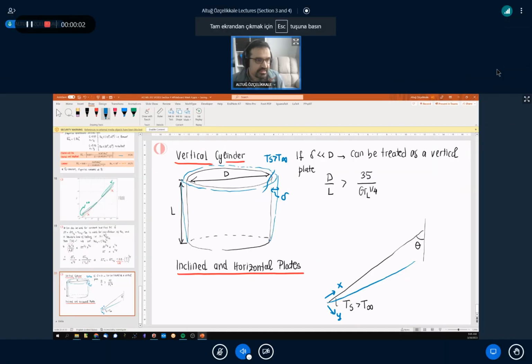Boundary layer forming like that, right? However, what's going to happen is when you consider a fluid element, this boundary layer is forming. However, previously the buoyancy force was in that direction, F buoyancy. Now the buoyancy force is going to be in that direction. It's that component, that's theta, it's that component of the buoyancy force that's going to scale with the gravitational acceleration, by the way. That's the gravitational acceleration over here, g cosine theta.